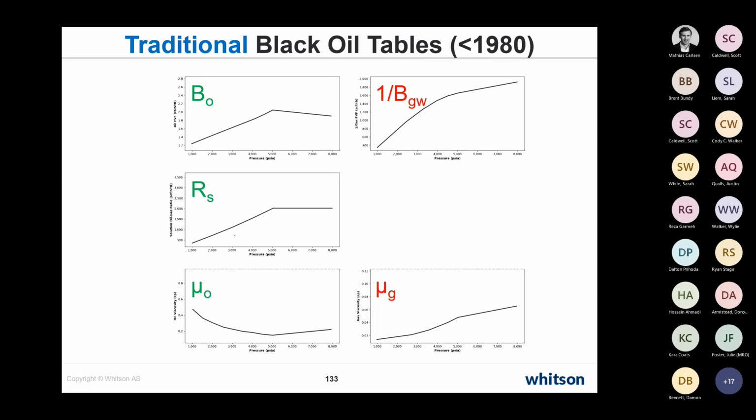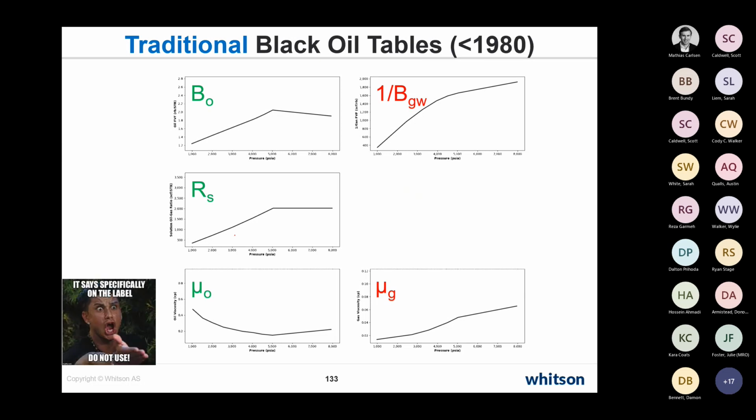I'm a little bit shocked that software still allows you to use these tables because they're always incorrect, and it's not like this big computational issue to include the additional component there. So when you, for instance, make the difference between a black oil and a liquid rich type of system in software, it's typically the difference of assuming that the reservoir gas has condensate in solution versus not. But do not use these tables in general. If it's not important, just the RV value will be very low and the amount of gas will be really small, so it won't really matter.